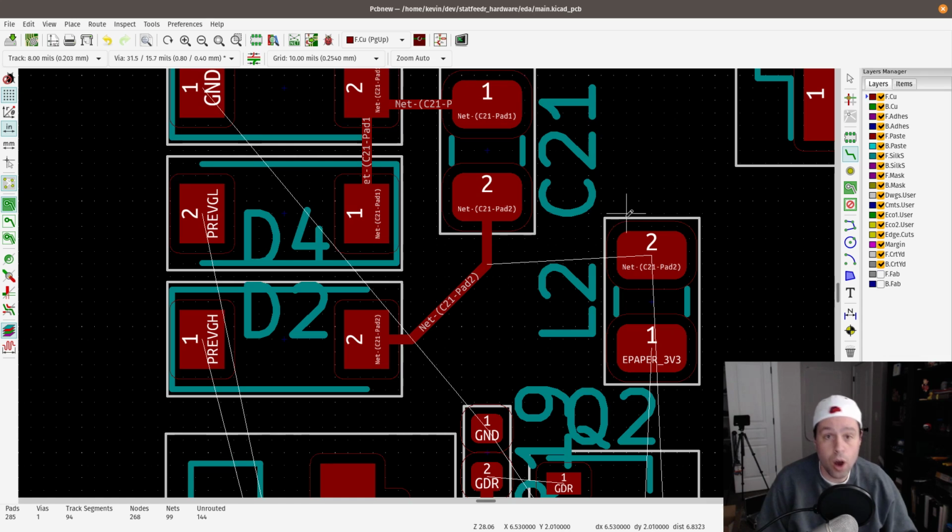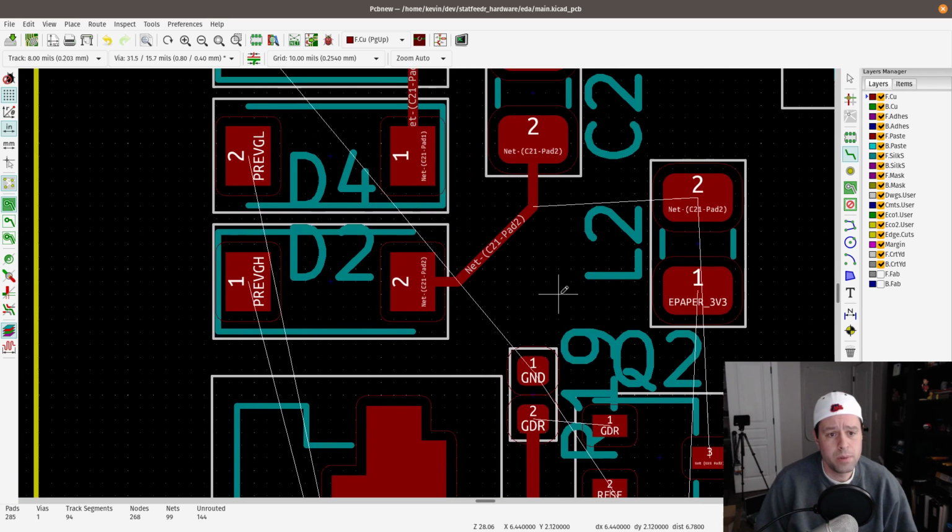And there is, and I'm not going to show this because I don't want to use it, a thing called an auto router. A lot of the EDA softwares have this, where you just click auto route and it will try and draw all the traces for you. Again, it'll just satisfy the rules of like minimum spacing and things, but it doesn't know anything about the parts and how they might need to have bigger traces in some places and smaller traces in others. It's just going to do its best to automatically route everything and say, hey, I satisfied the net list. And so that's not what we want. And so that's it. Like I said, that's the name of the game.